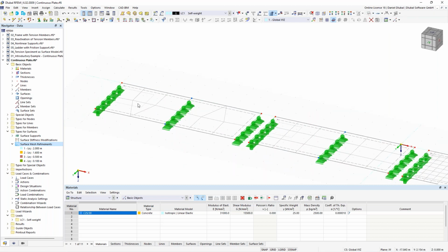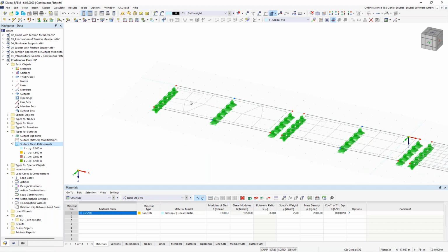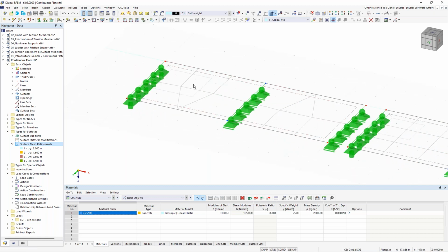Yeah, this is the FE mesh, and at each FE node there will be results. And between these FE nodes and the results, they will be interpolated in order to get a smoother result distribution. And as you can see here, because we have a very rough FE mesh, this FE mesh and this quality is not so good.